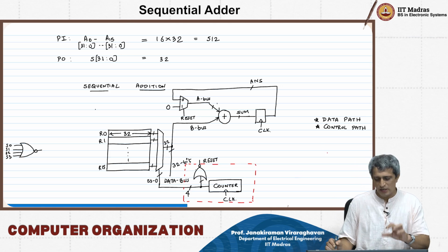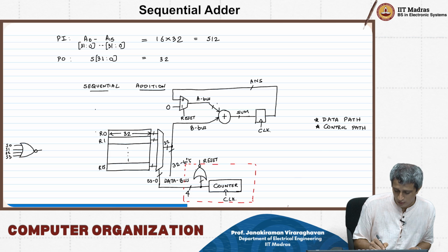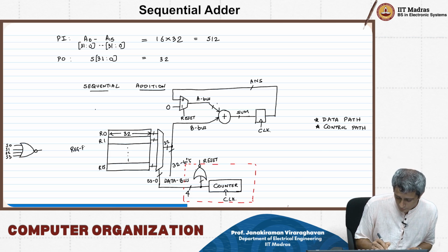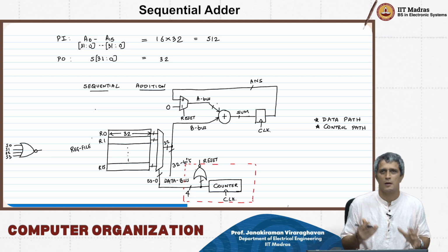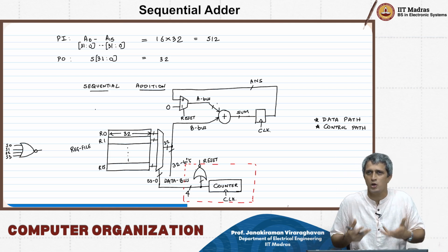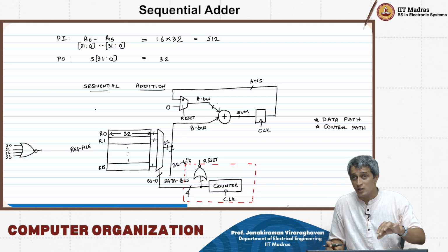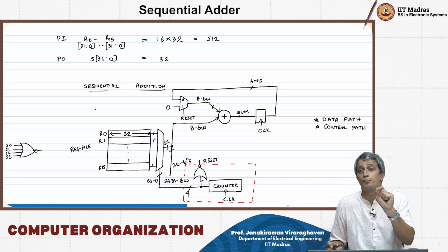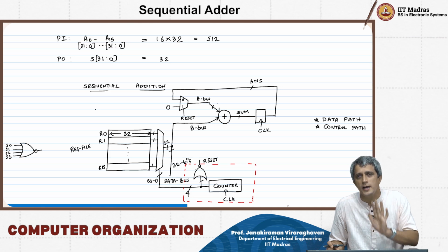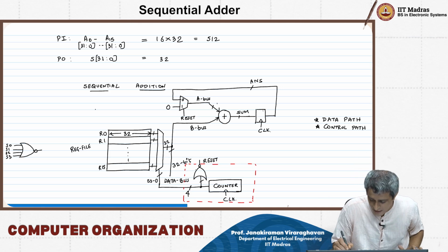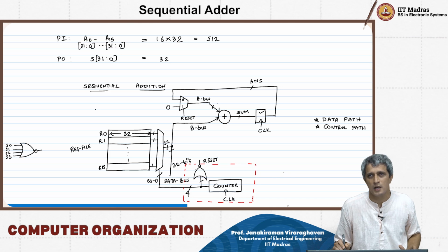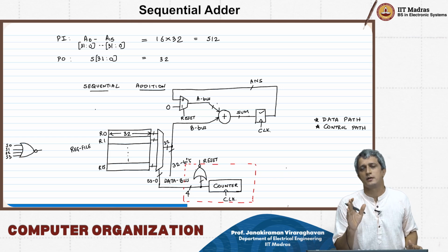By the way, this collection of registers here is what we call a register file, a bunch of registers from which we can do some operations. What operations, we will come to right now. These registers are purely allowing only read to be done. On the other hand, this register here is allowing only write to be done.